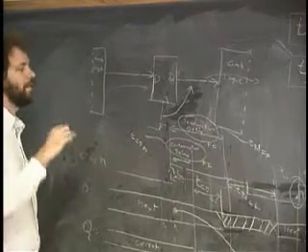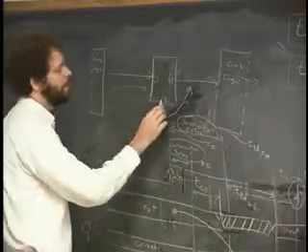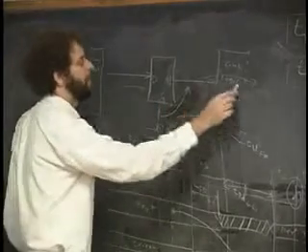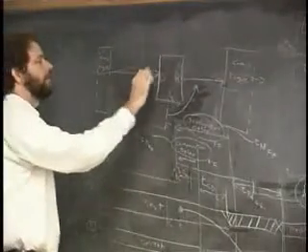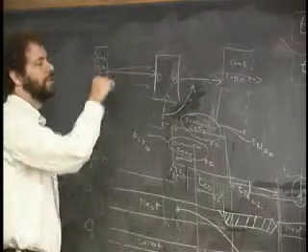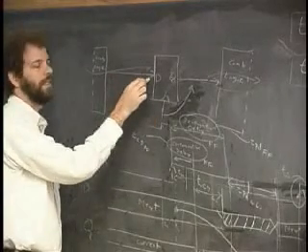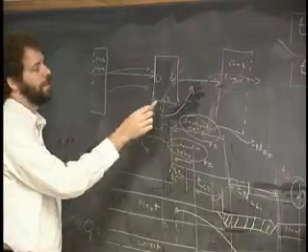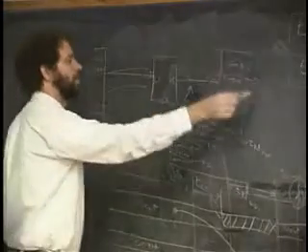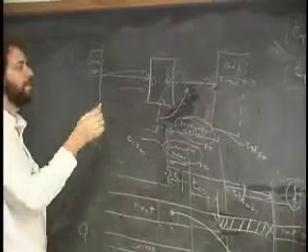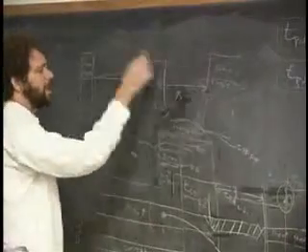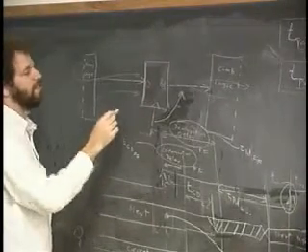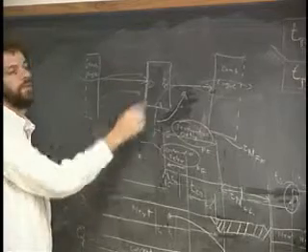Again, the constraint on the hold time is to make sure that the data doesn't race around here, the contamination doesn't race around the loop faster than the amount of time we expect this to be held after the clock goes off. And that says that the sum of the contamination delays, or another way of saying it, the sum of the minimum propagation times around the loop, has to be more than the hold time.